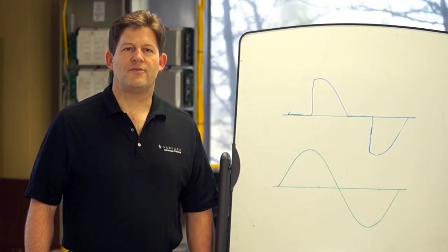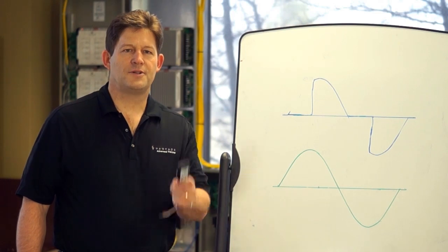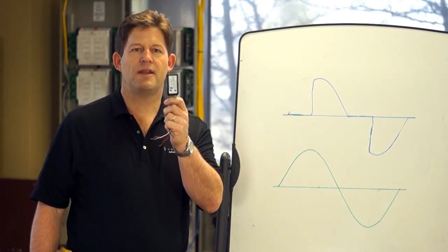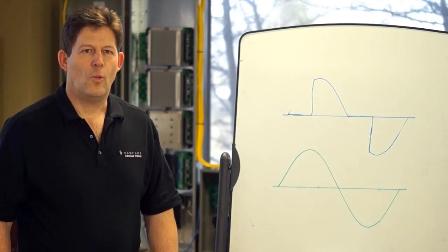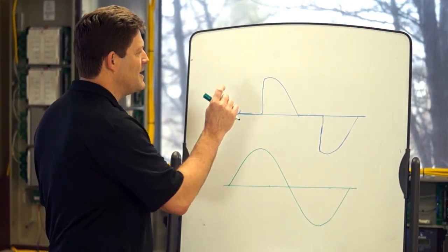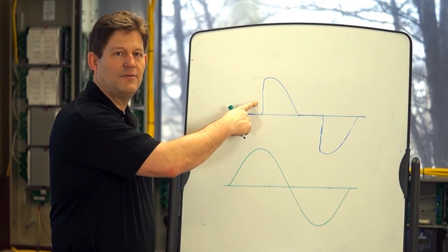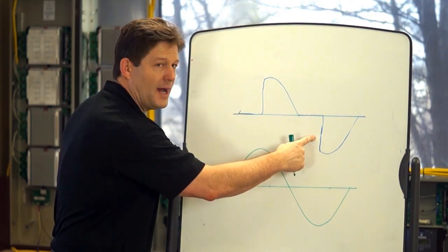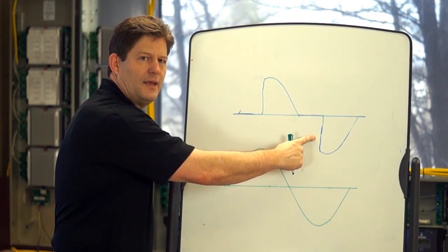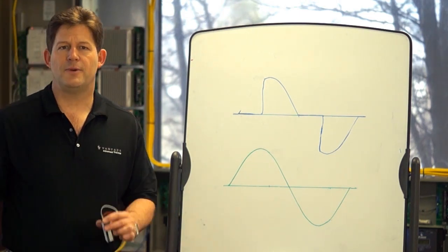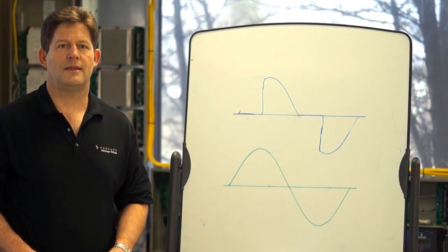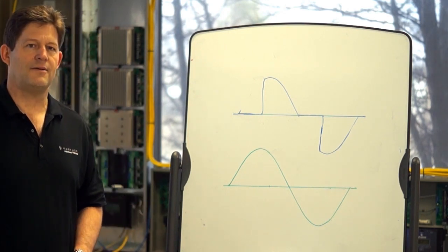At one point in the history of light source development, the electronic transformer was introduced with a very different set of characteristics from those of a magnetic transformer. One key difference is that it is not at all compatible with a sudden voltage rise that occurs twice during each cycle in the scenario that we've just looked at. So there's a compatibility issue between the electronic transformer and the standard dimmer. You cannot use the two together.